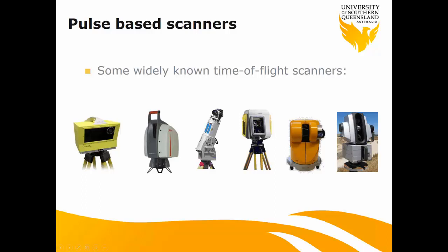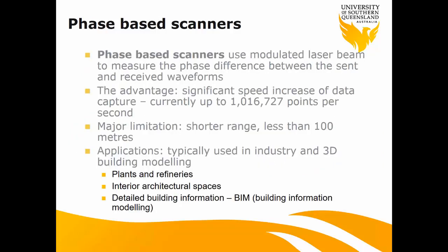And this one is a Trimble. I can't remember exactly which model this one is. It is quite commonly used in mine surveying in Australia. It is a time of flight based laser scanner. You can see it is so big and also quite heavy, maybe 20 kilograms. But it is very reliable and very strong, so suitable for use in the mining industry.